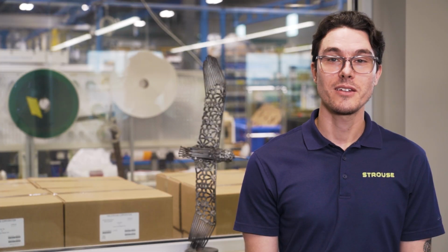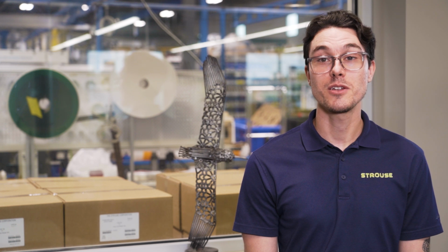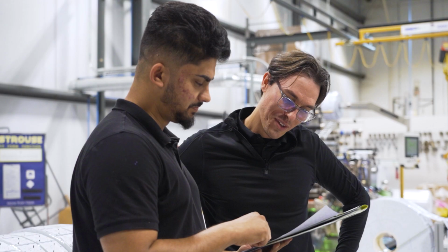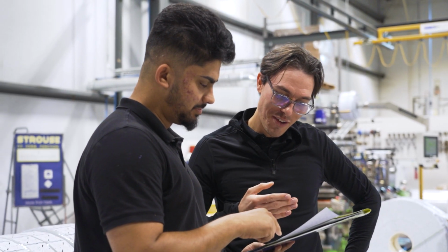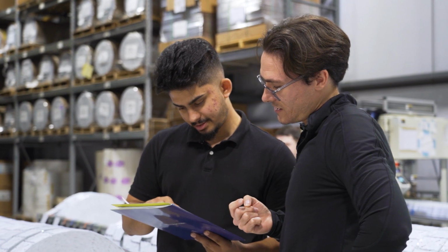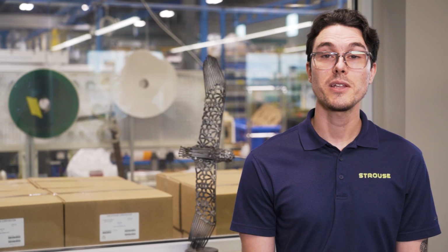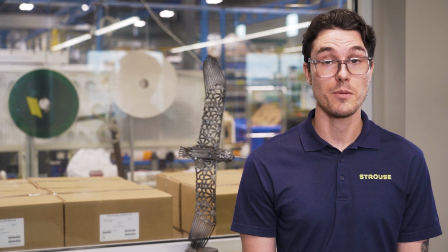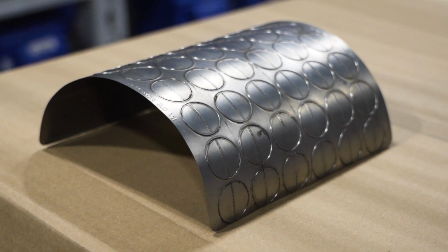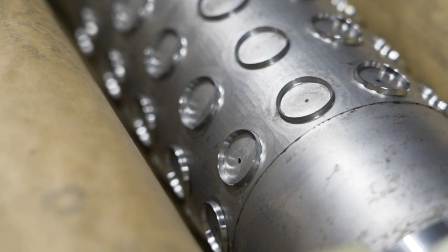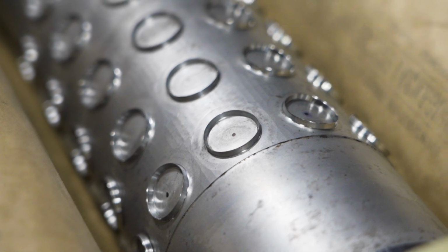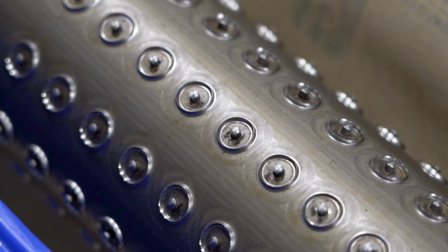Tooling lead time can significantly impact your process if it is a new die cutting project for the converter. If this is your first order with a converter and the process isn't entirely laser or digital knife, custom tooling must be manufactured. Tooling lead times can vary depending on the type of tool. Simple flex tools can get there in a matter of days, whereas simple hard tools will take weeks. More complex hard tools can take months to produce.